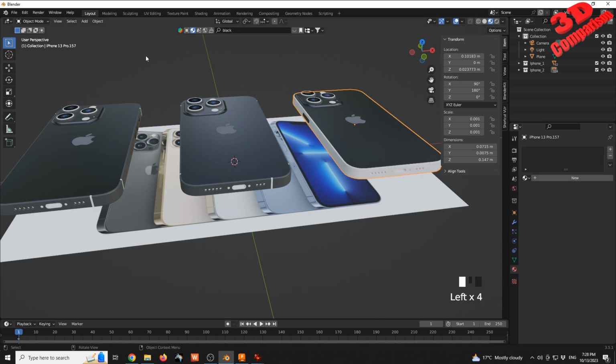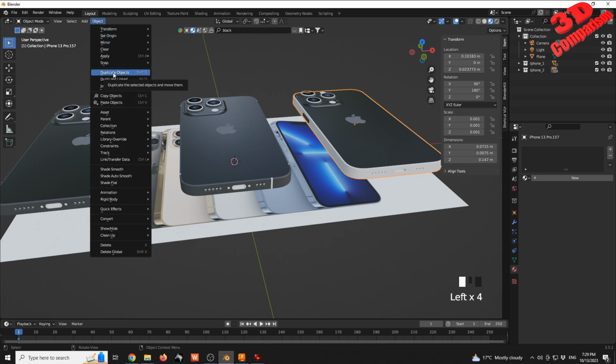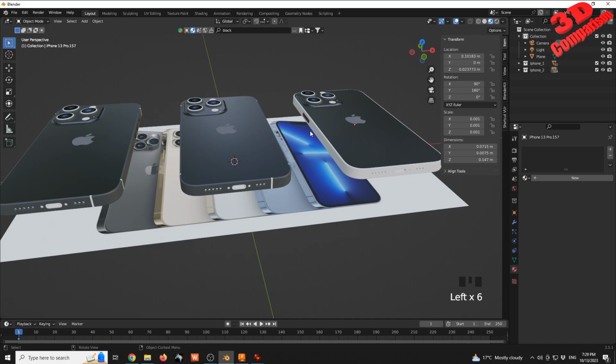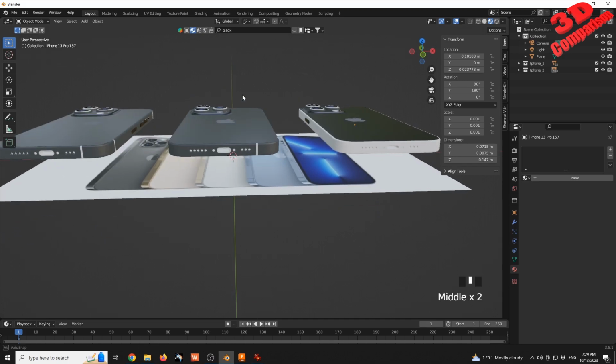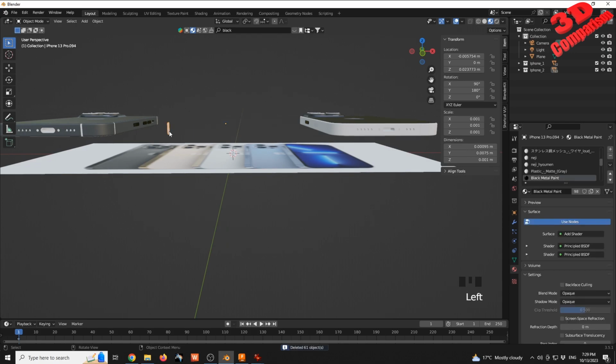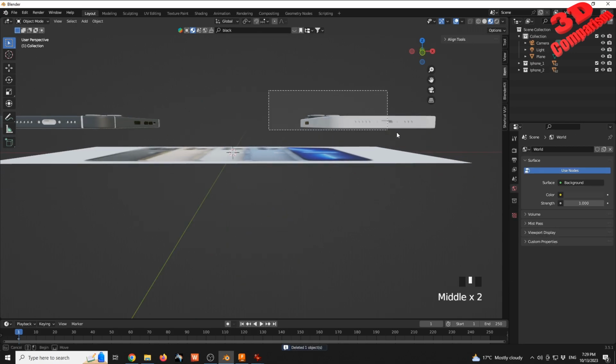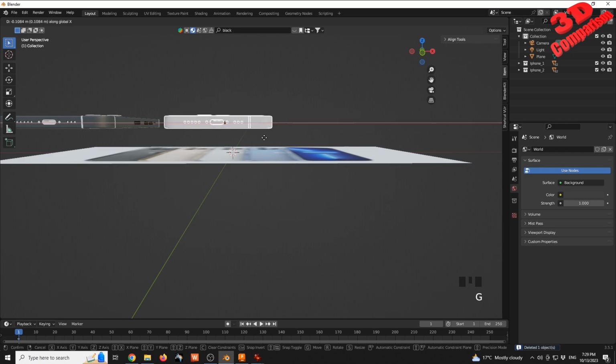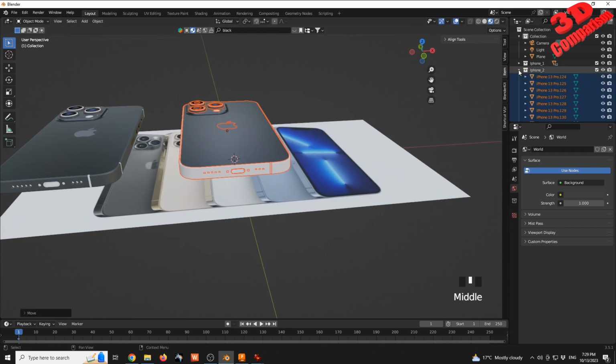Yeah, so when we made that copy, we should have gone with duplicate objects, not duplicate linked. Then they won't be linked. So we can just have this deleted. We can have that selected again, move it back, and yeah, this will now be iPhone 2, so we no longer need to create that again.